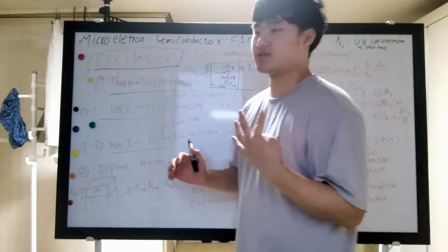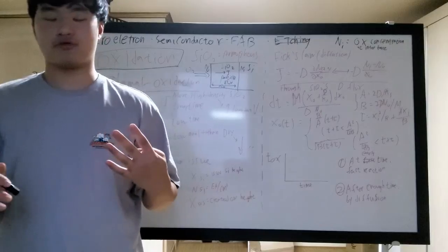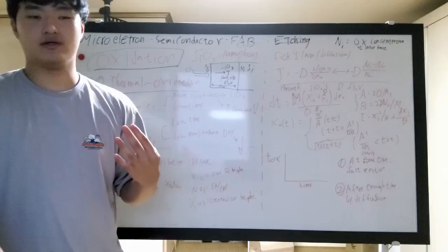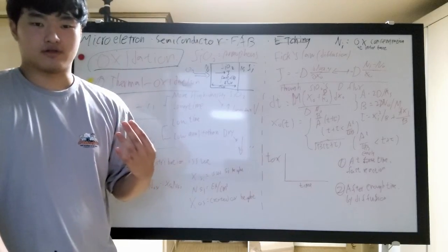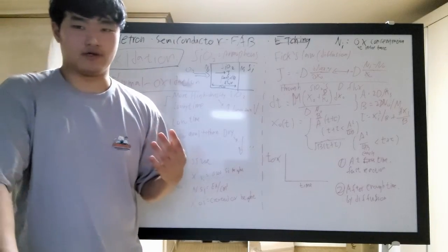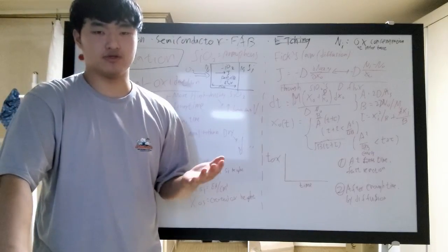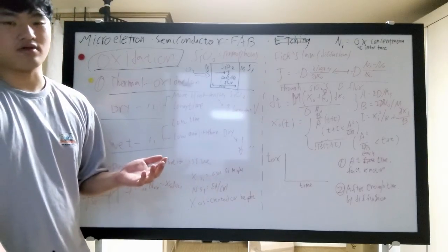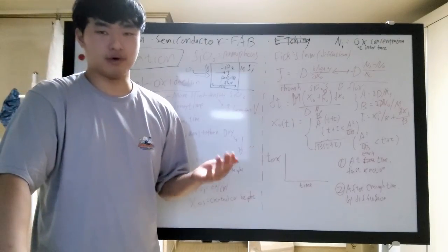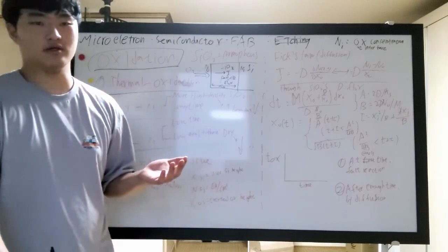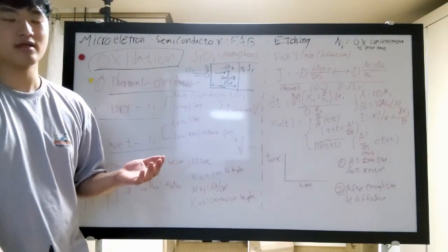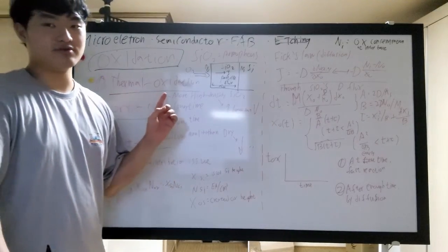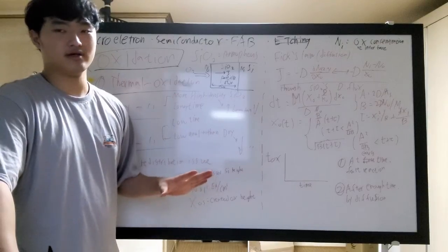In the first video of this class, we talked about lithography. For lithography, we needed a mask that can block the light from reaching the unwanted areas that should not be reacted by the light. There are many masks that can block the light from being injected to the silicon wafers, and the most common will be silicon dioxide. Silicon dioxide is widely used.